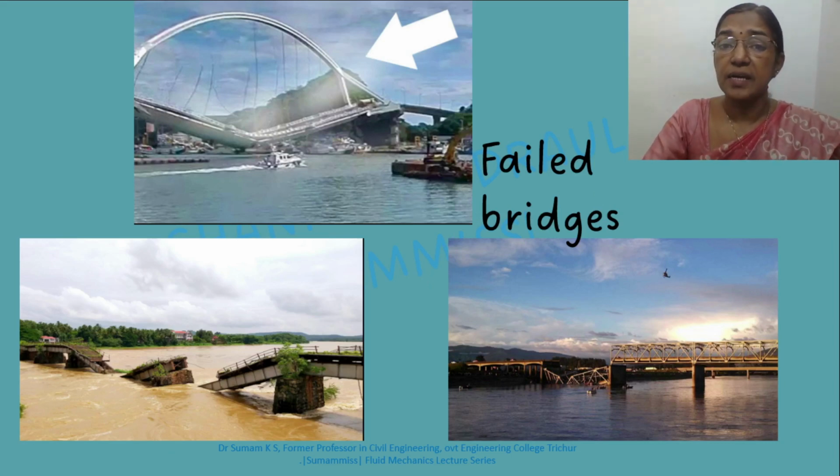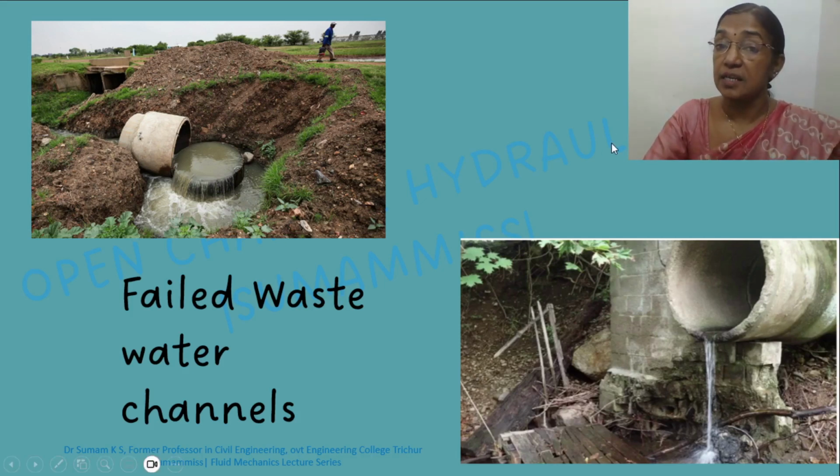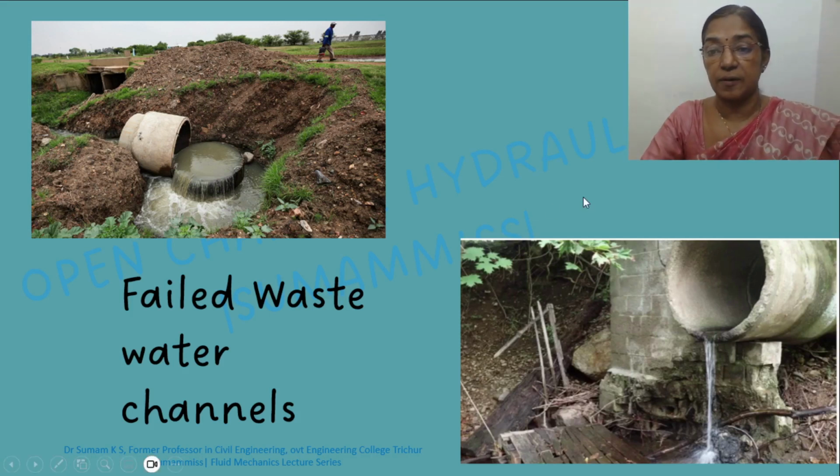Another important application is the design of wastewater transportation systems. The failure of this wastewater transportation system is vital as it causes many health issues and other menaces. Proper design and utmost care is taken in the design of wastewater channels as the low velocity in the channel will allow the settlement of suspended matter, which reduces the carrying capacity of this channel and aggravates the whole situation.